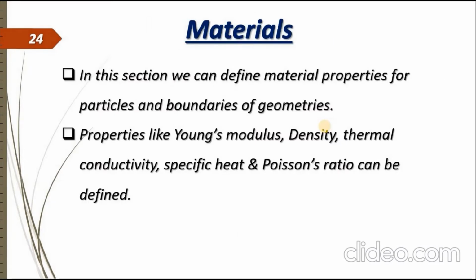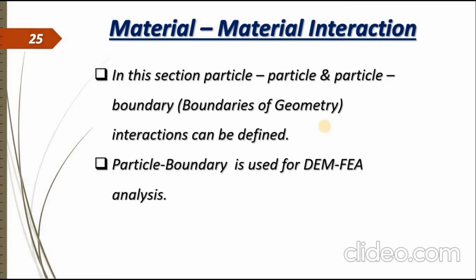In the materials section, we can define material properties like Young's modulus, density, thermal conductivity, specific heat, and Poisson's ratio, and properties of particles, boundaries, and geometries as well. In the material-material interaction section, particle-particle and particle-boundary interactions can be defined, and particle-boundary interactions are used for DEM-FE analysis.